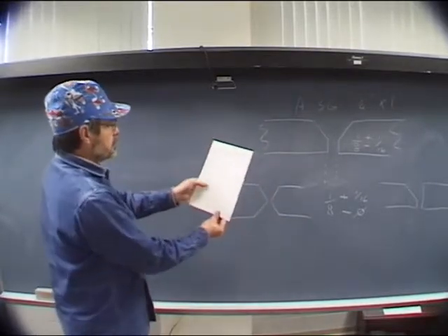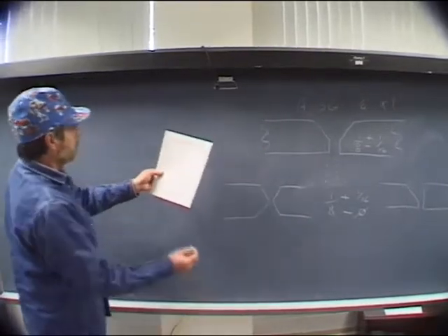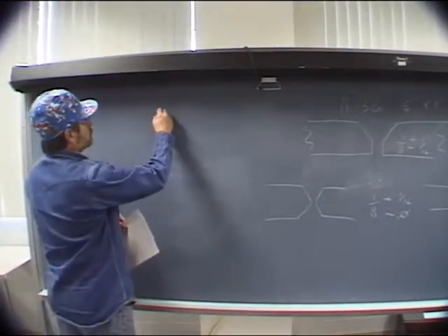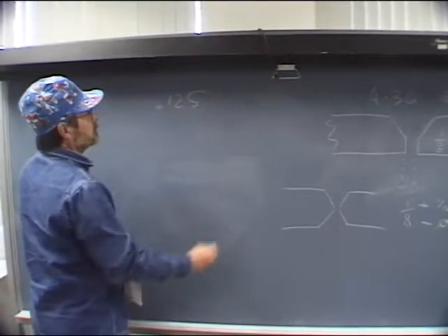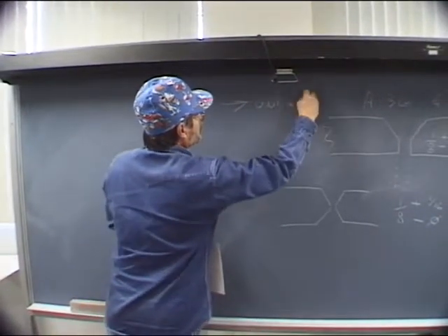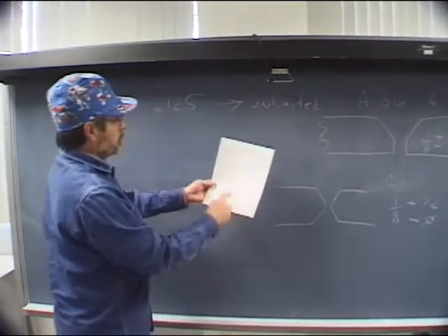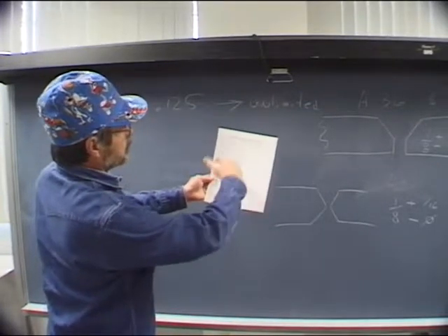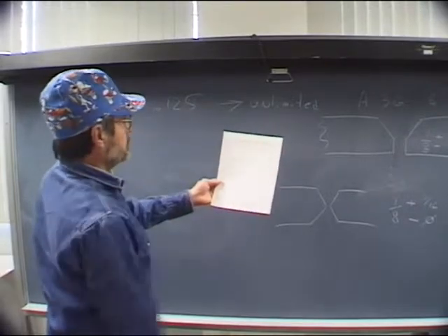See, we're establishing ranges now. And so the thickness range might be down to 0.125, which is 1/8 of an inch, to unlimited. So here we would have 0.125 to unlimited, and then the fillet welds are unlimited in size.